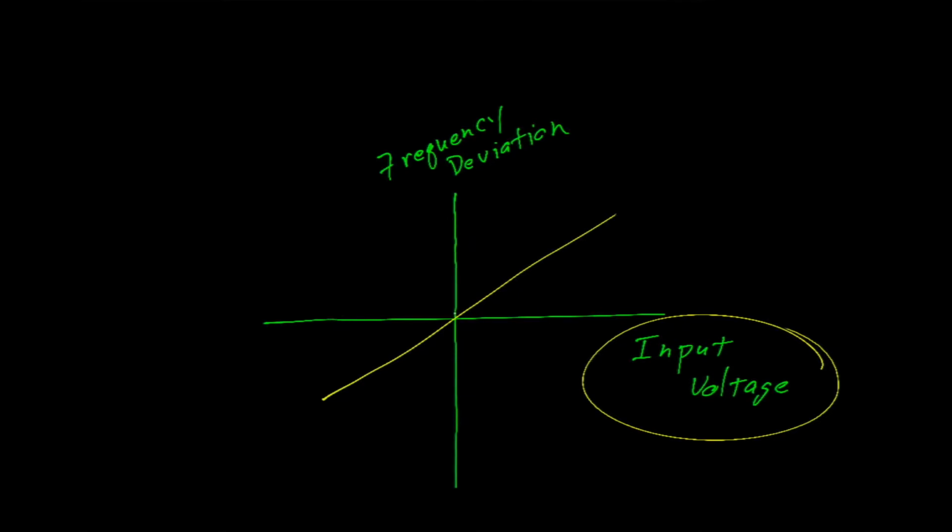Cover your ears because we're going to turn on that annoying sound again. You can hear the frequency changing as it goes up and down. Right? It's going up and down, so very annoying. The reason it's doing that is because the input voltage is going up and down, which means the output frequency of the oscillator is determined by the input voltage.